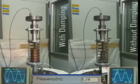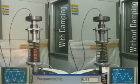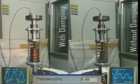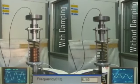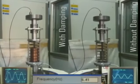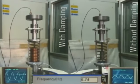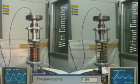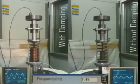Look at the right hand side and see how vigorous the oscillation is. If you look at the top plate, and you can also see it in the oscilloscope. And if you look at the left hand side, you would see that most of the vibrating energy is getting transferred to electrical energy, and hence you get much less vibration amplitude in the left hand side case. So, that is typically what you will see in a system which has a damper in it.